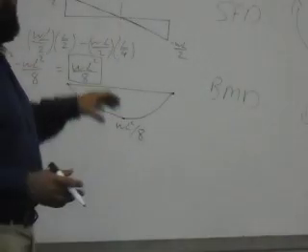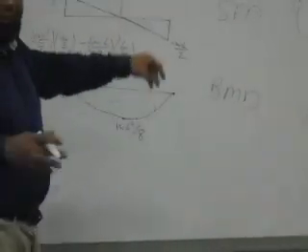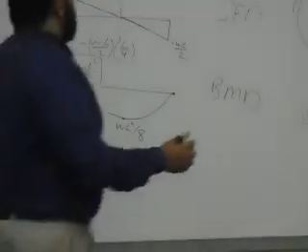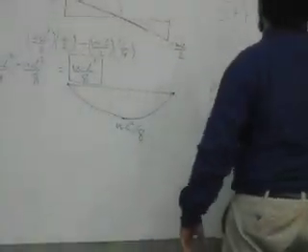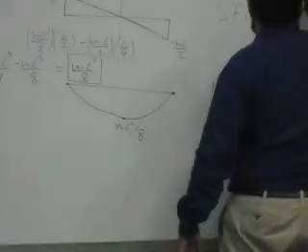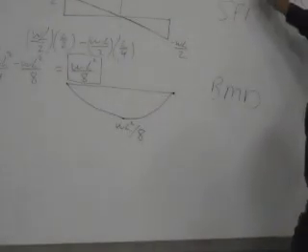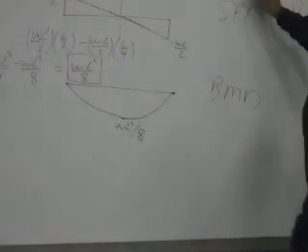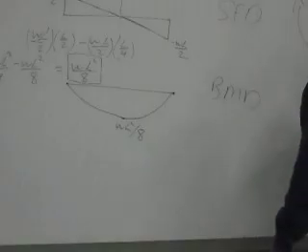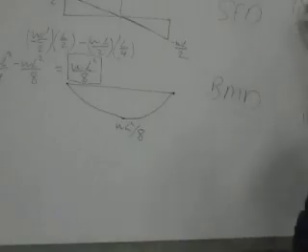Right? But why is it very important? Because if I'm having any support condition, watch out, if this thing has double cantilevers for example, and this is a distributed load, I can use this case. How? If I go and draw the bending moment diagram, something like that, I'll find what? I'll have a negative moment here, and another negative moment there. Okay? And there is a value here that I don't know. So simply speaking, look here. You connect these lines and drop a value of what? What's this ordinate?